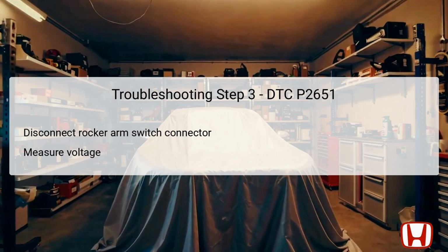However, if there is no voltage detected, troubleshooting will then focus on other circuitry aspects leading to the switch. This thorough voltage check provides critical information regarding the status of the oil pressure switch and the associated wiring. The fourth troubleshooting step focuses on checking for continuity in the powertrain ground PG wire line. This involves first ensuring that the vehicle is in the off/lock mode to safely perform diagnostics.